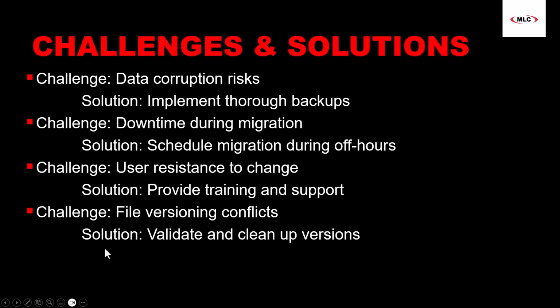Now, when we're doing migrations, you can always run into the risk of what we call file versioning conflicts. What that means is if users have not put their data in the appropriate location, for example, if they haven't yet saved it to the server, or they haven't yet checked it in to the vault, obviously when we migrate, it's not in the vault, so it's not there to be moved.